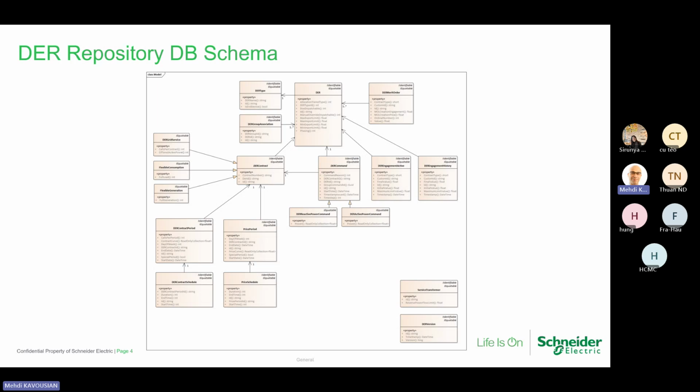And they tell you, okay, I am doing 300, but I can offer you 100 kilowatts to play with. That means you can send me a command between 300 and 400 on the positive side, and on the negative side between 300 and 200. So you give 100, and we call it offer active power. It can be a positive number or a negative number. So it's a bit different from the other two. These are absolute values based on rating. This one is based on the amount that is being generated at that moment. You know what I mean?